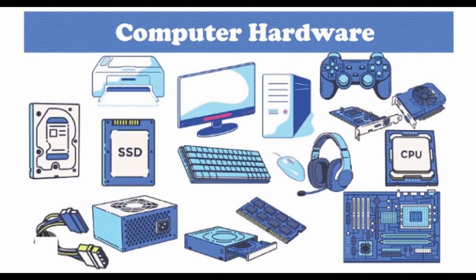The chipset, which includes the North Bridge, mediates communication between the CPU and the other components of the system, including main memory, as well as South Bridge, which is connected to the North Bridge, and supports auxiliary interfaces and buses, and, finally, a Super I/O chip, connected through the South Bridge, which supports the slowest and most legacy components like serial ports, hardware monitoring and fan control.